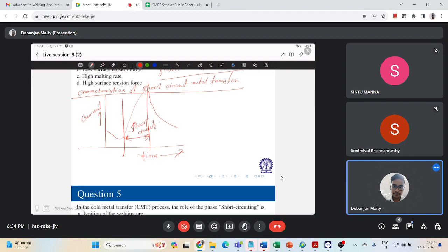Depending on your arc gap, the metal droplet detaches from the filler and fuses with whatever material is still molten and also the base metal. And again, your wire will move forward to create another arc, and all these phenomena happen several times in each second. This is also a pulse mode operation. Here, it provides a controlled method of material deposition by a sophisticated wire feed system at a very low thermal input, and in effect, it needs high-speed digital control technology.